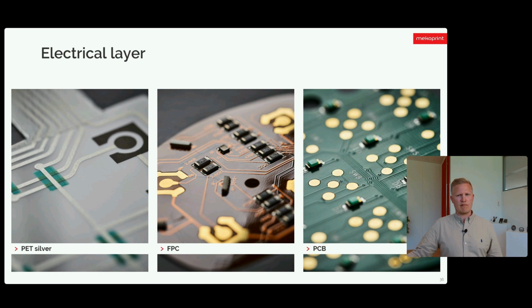PCBs have the same functional features as FPC, but are normally chosen if there are requirements for the stiffness of the keypad in connection with the mechanical integration. But also if there are many soldered components on the PCB, this might be the way to go.